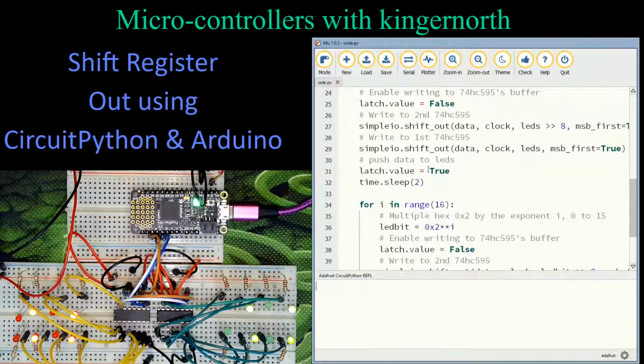What we see when I look at the bottom here are the hexadecimal values I'm reading out. We should see these come out as 1248, 1248, but each time we add another 0 to the right-hand side. If you think about this in hexadecimal, that's actually 8000, which is going to be the 15th bit, counting from 0. In binary it would be 1000000000000000. It's quite a ways up there, and I may have missed a zero in there. But the whole idea is this number goes out here.